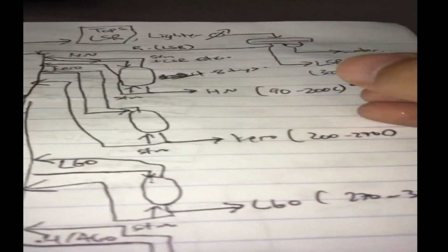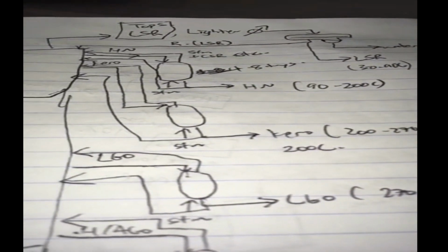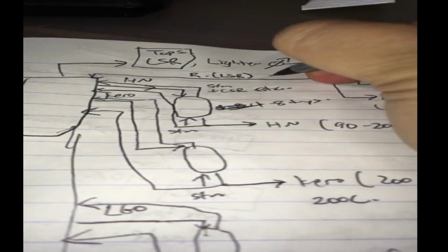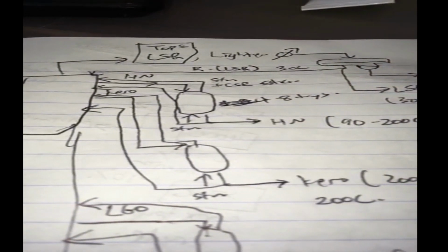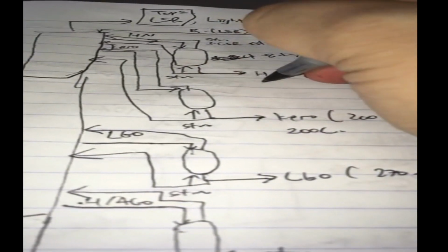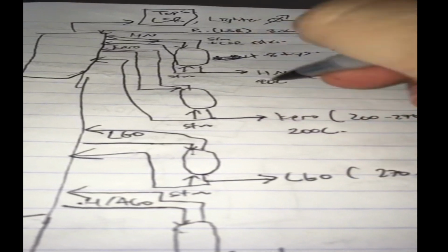And secondly, you notice that this kerosene will be at 200 degrees when it just cools. And this reflux rate is at 30 degrees. Roughly 30, 40, 50, something like that. And this heavy naphtha will be at 90 or less. This will be at 270 or less.